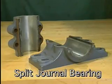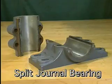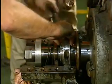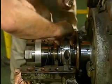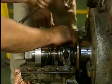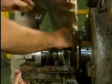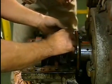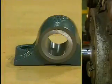A split journal bearing consists of a two-piece bearing mounted in a two-piece housing. The advantage of a split journal bearing over a solid journal bearing is that it can be separated into two halves. A split journal bearing is easier to service since it can usually be separated and removed from around the shaft without removing the shaft itself.